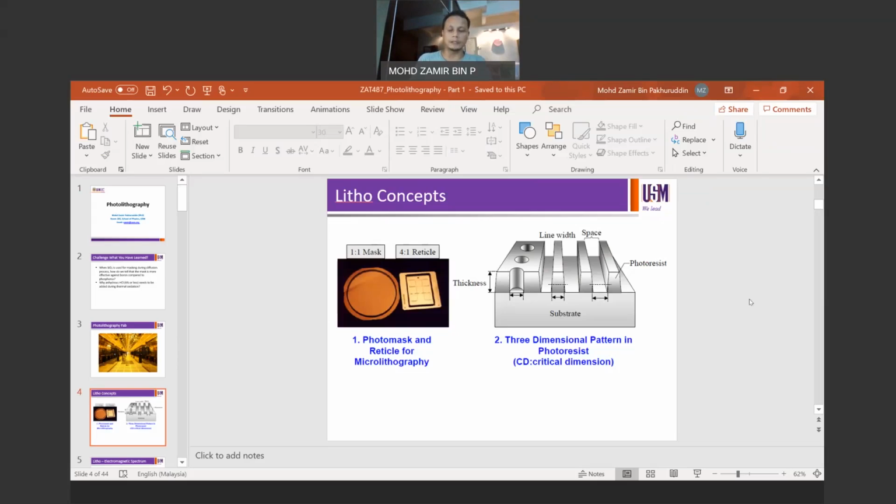As I said before, you're going to need to measure the line width, which is called critical dimension in lithography. We typically call it CD, or critical dimension. It usually reflects the width of the line here. So the width of the feature is called line width or CD. If you talk about a hole on the left hand side, it usually refers to the diameter of the hole. So it's also called CD, or critical dimension.